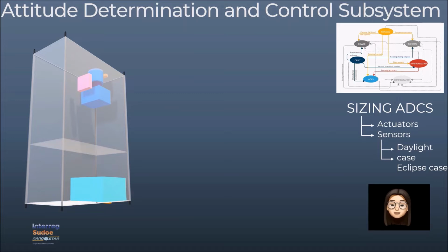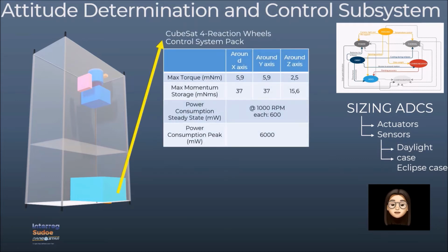This need for 3-axis stabilization and the precision required by ground pointing during data transmission time leaves reaction wheels as the best option of actuators. To recognize the position of the vehicle, there are several sensors that provide an interpretation of the vehicle orientation. Since the chosen actuators are mechanical, magnetometers have been discarded in order to avoid mixing different types of components.